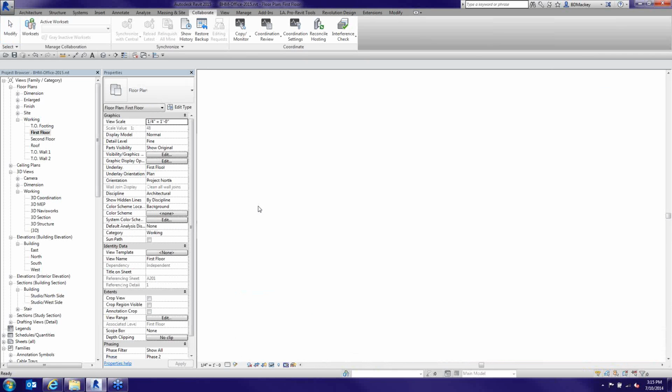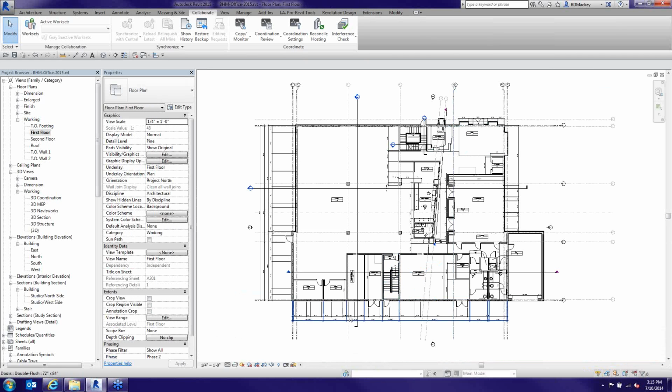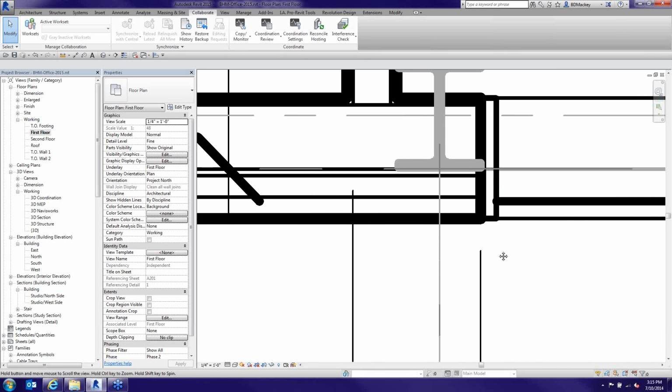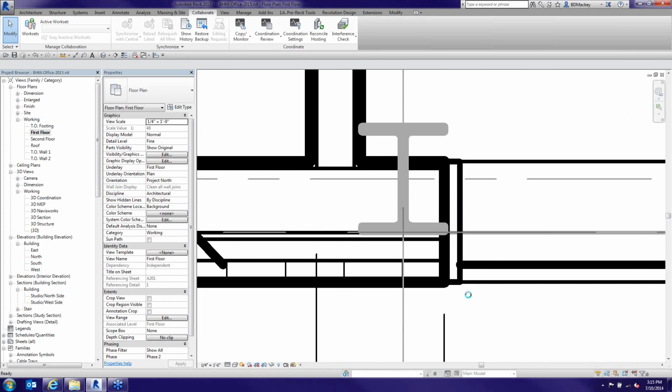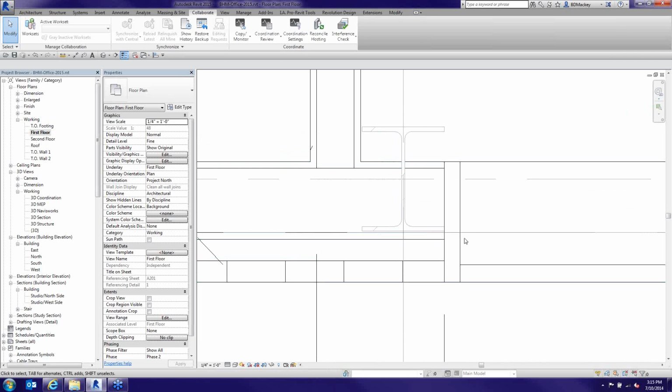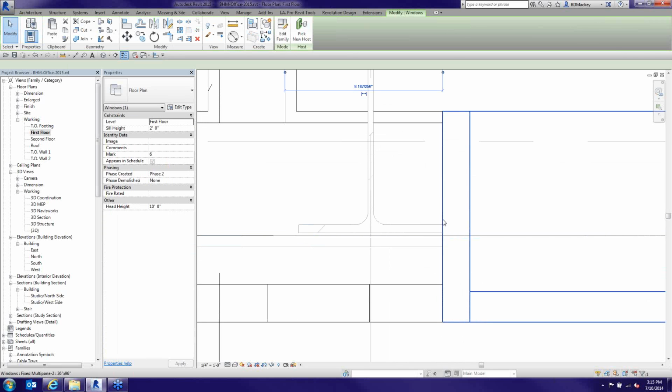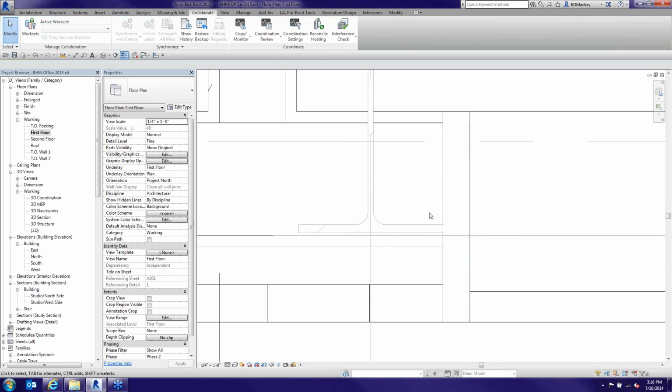I did. So the one thing I like to show is what it doesn't do, what Navisworks will do. If I come down here and zoom in, I'm on that same structural column, but I'm going to zoom into this at level 1, where Navisworks blows us out of the water. Because this really isn't a feasible type of construction. I don't think I'm going to be able to mount a window right next to a structural column. But in the Revit world, this is not a clash because there isn't an interference. Objects can be touching on their surface.